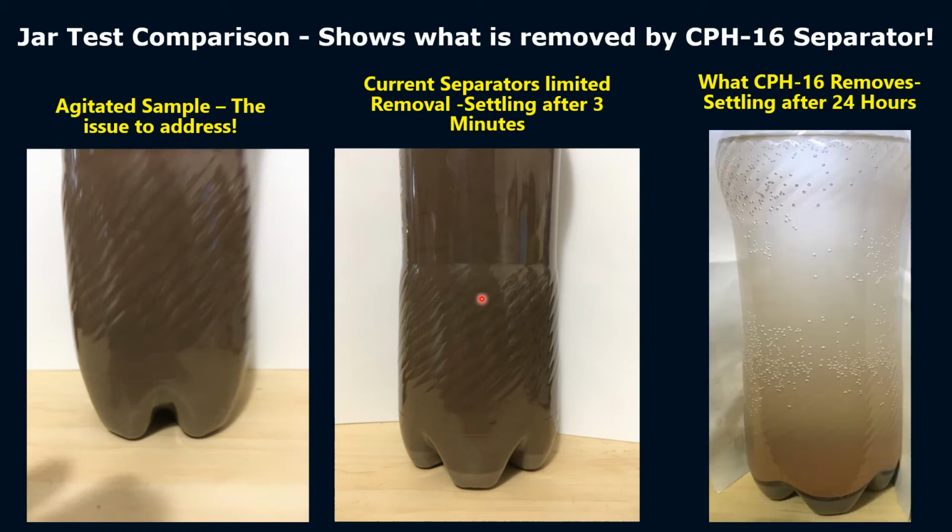And then if you look at our sample, we agitate it, and this was based on the video that you'll see, but 24 hours of settling time, and you can see not only did I get the sand that we got down there, but I got a thin layer of silt and clay. Actually, there's 3 or 4 layers here. So dramatic improvement in terms of the efficiency of removal of solids by this separator.